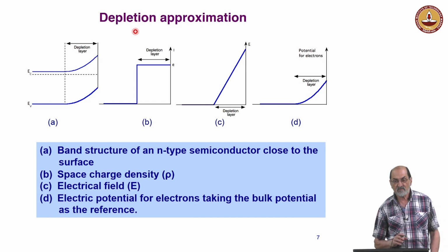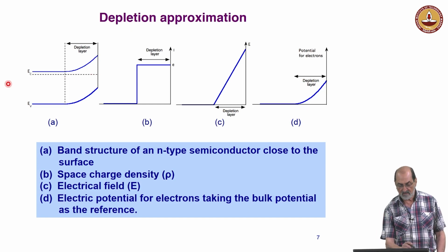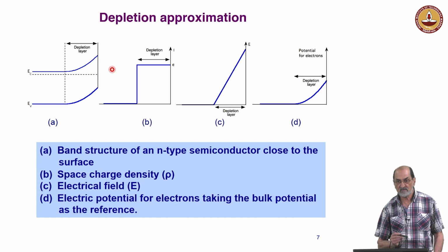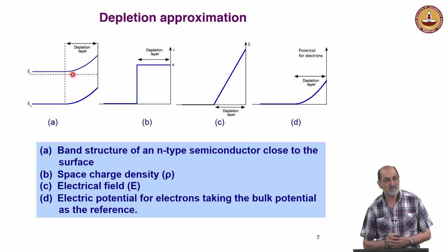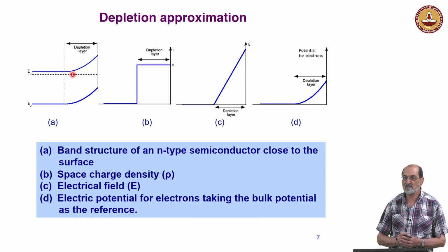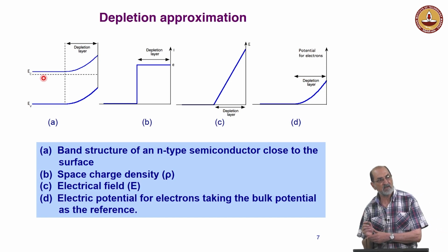So, what happens then at the surface of the semiconductor when the Schottky barrier forms? We have essentially a depletion region. Those electrons have gone to the surface, towards the metal. Essentially, as soon as the bottom of the conduction band goes up, the density of electrons in the conduction band decreases abruptly because it depends exponentially on the difference between the bottom of the conduction band and the Fermi level. Do you have in mind the formula? It's an exponential, e to minus (EC minus EF) over kT.